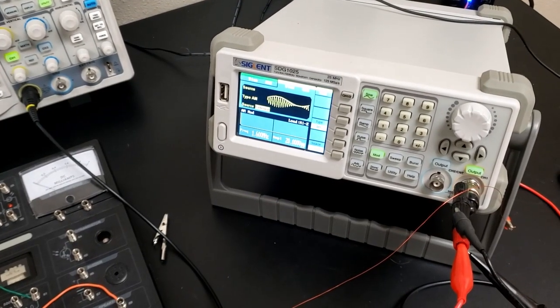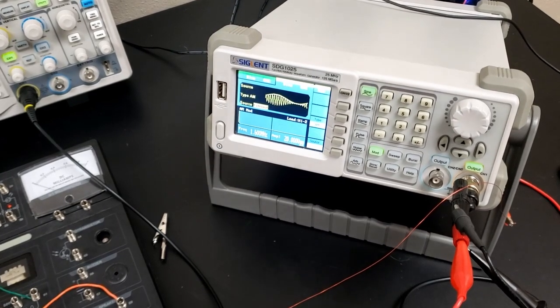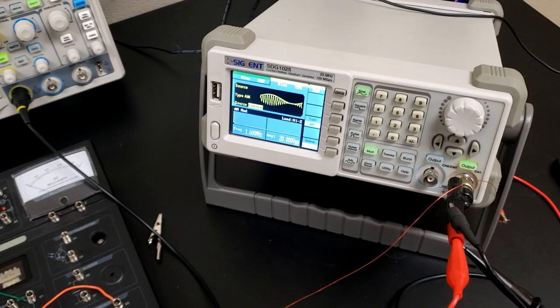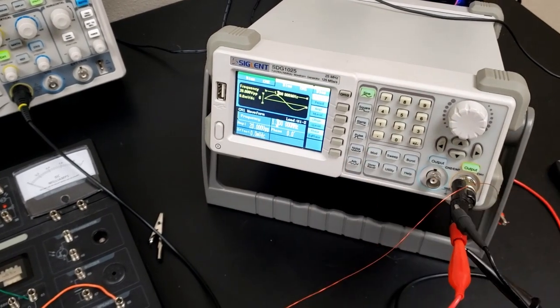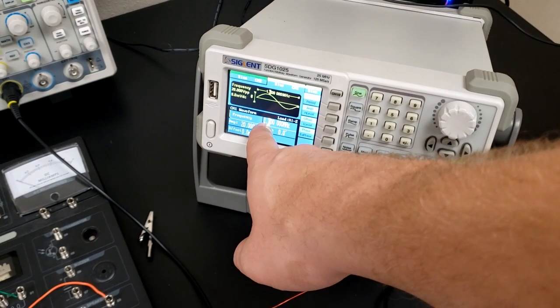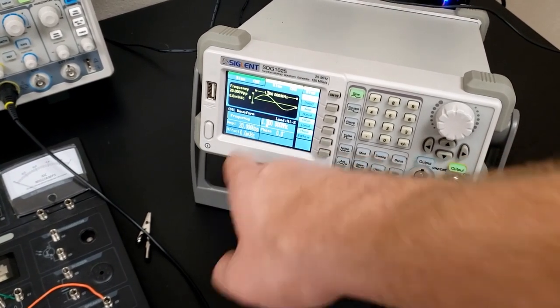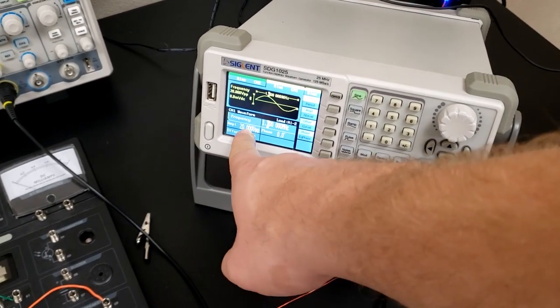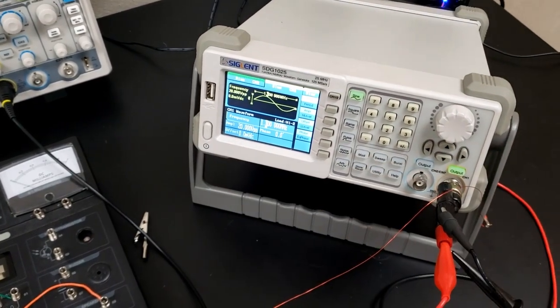Okay guys, so here we are. We've got the radio set up, but before we show you that, I wanted to show you how the signal is being modulated. So what I have here, I don't know if you can see, but I have my frequency for my carrier wave set to 1.6 megahertz, which is within that range that we're looking for an AM signal. And then I have my amplitude of my carrier wave set to 20.